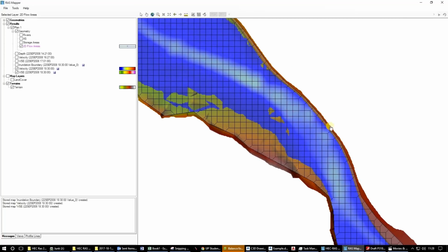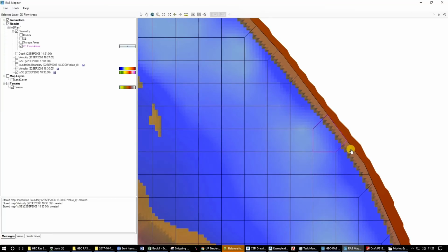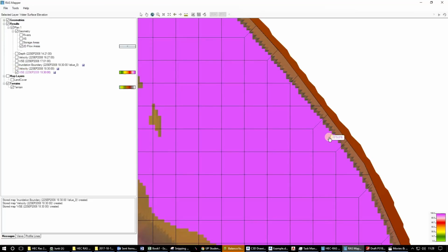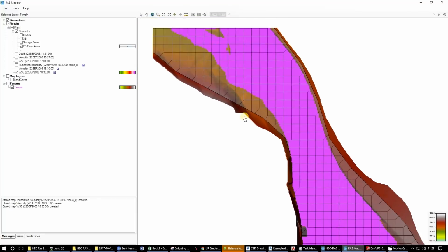If we look at the other side of the river, we can see that it is close to the boundary, but it is actually against that wall. We can check this by looking at the water level right there. As you can see, the water level is around about 1579.9, so let's call it 1580. And then if we look at the actual geometry depth or the terrain, over there it's 1581, which is rather significantly higher than the water level, so we can assume that the water is not overflowing onto the road. That's one neat little thing that we can check.